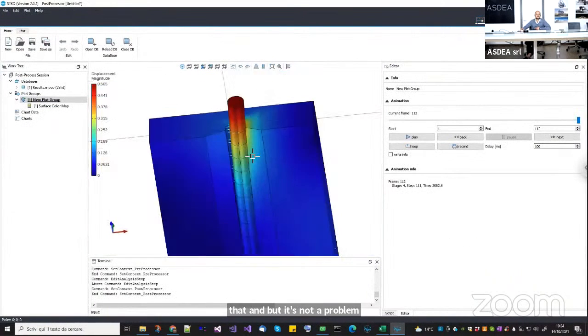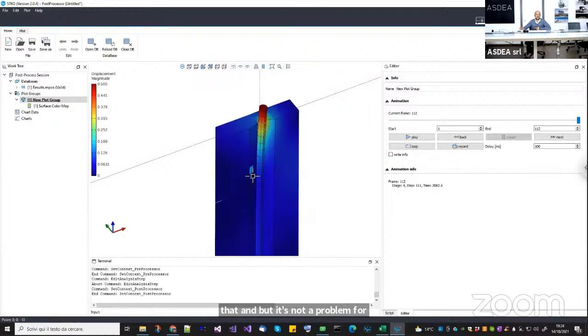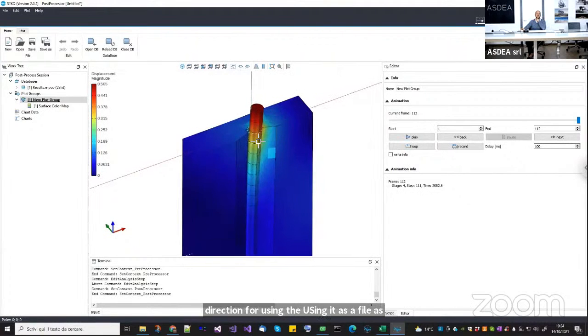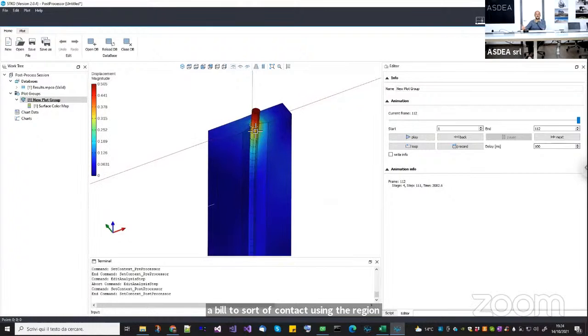I can visualize them, okay? Okay, so in this case, you have learned all the 3 different ways you can use the same contact element. So as a node-to-node contact with local axis, as a distributed contact using the element normal contact direction, or as a pile, as a beam to solid contact using the rigid gap, okay? So these are 3 different options, all with the same element.